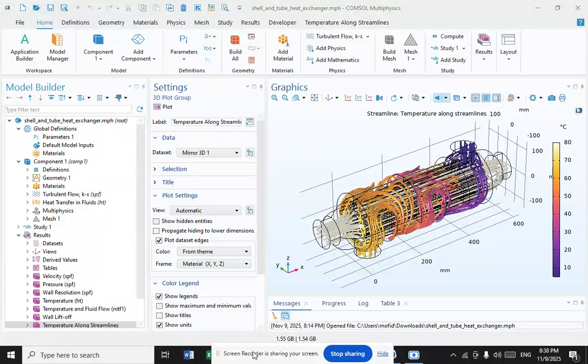Advances in gasket and brazing technology have made the plate type heat exchanger increasingly practical. In HVAC applications, large heat exchangers of this type are called plate and frame. When used in open loops, these heat exchangers are normally of the gasket type to allow periodic disassembly, cleaning, and inspection.